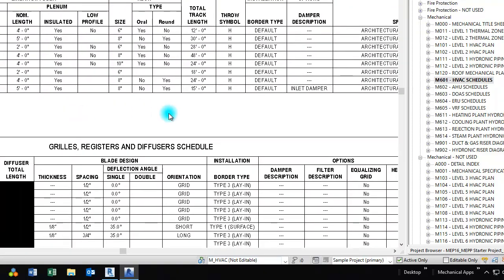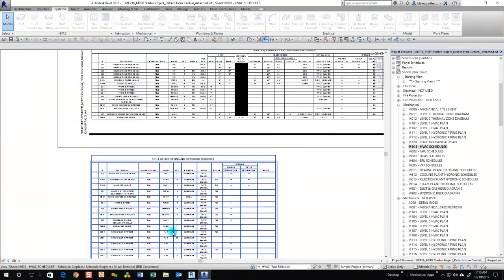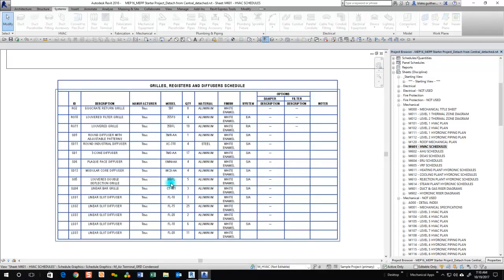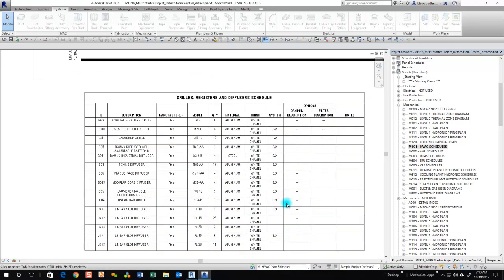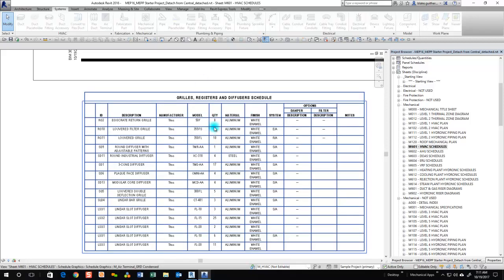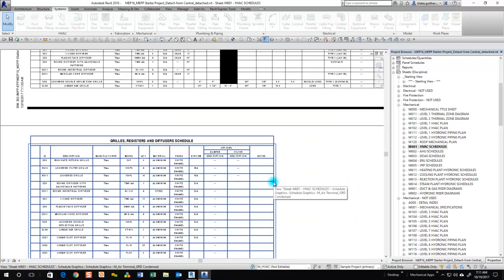So you guys can decide how much you want to show on your documents. We've also provided a more condensed schedule, which over the years has become more of a common situation, where you're just calling out an ID, description, basic stuff, but no sizes, refer to plans for sizes. But let's just remember why we were doing that: because we didn't want errors between the schedule and the drawings. Now they're the same pieces of information, so that concern should be alleviated. I did include quantities here, but in this case, that contractor would have to go and look at all the different sizes, so it's a bit more time for him and potentially could open up more errors.